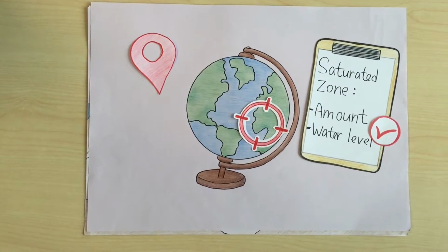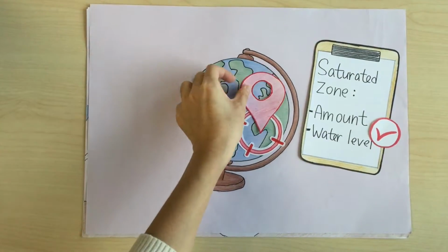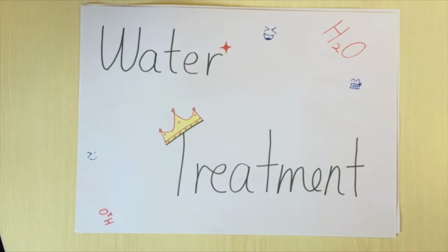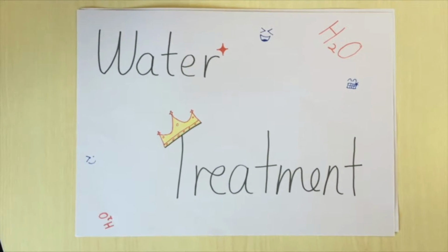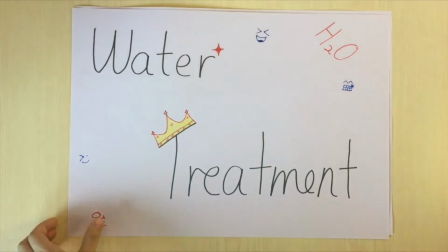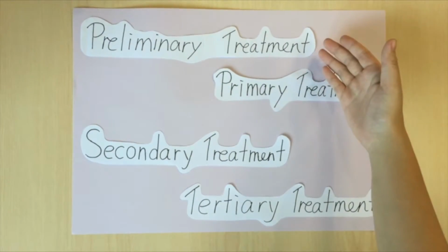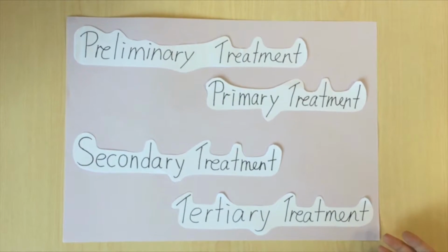After all this research, we can obtain enough information on the source. If this source is available for us, we can pump the water from this area to our plant and start the first part of the water treatment. As the contaminated water may contain solid impurities, the processes based on sewage water treatment are used to purify the water before filtering the arsenic. There are 4 main steps: preliminary treatment, primary treatment, secondary treatment, and tertiary treatment.